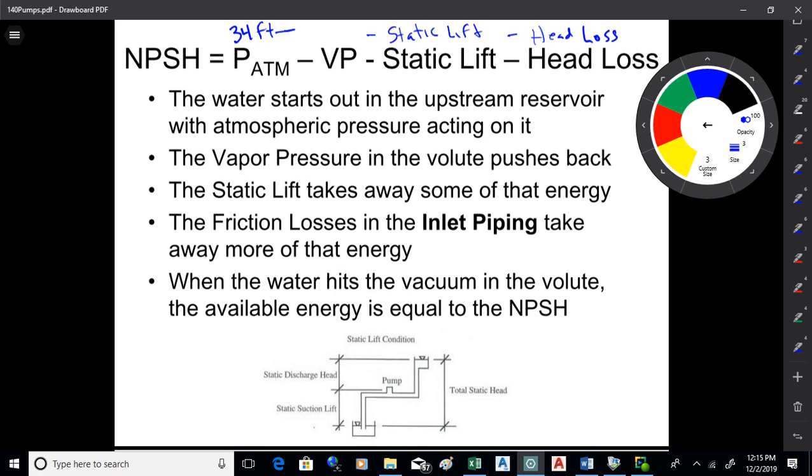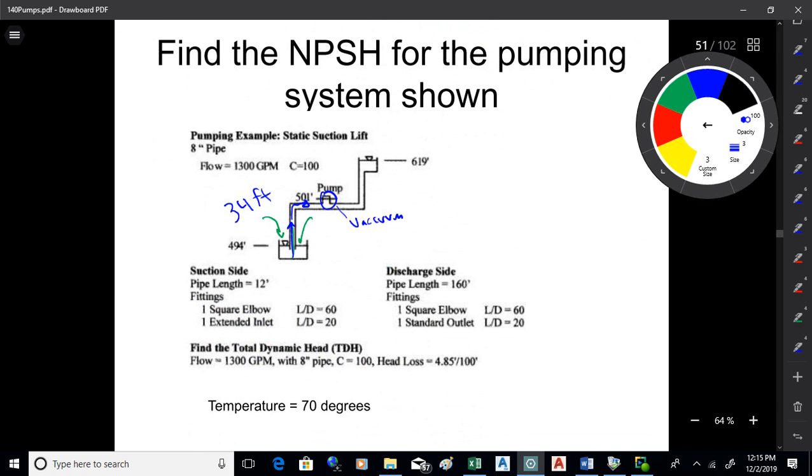So you have to lift the water, and you have head loss as you lift the water. But there's one other thing, and that is that you don't have a perfect vacuum in the pump. Even though it's throwing the air out, there's a certain temperature that's going to evaporate some of that water. So it isn't a perfect vacuum in the pump. It's a partial vacuum.